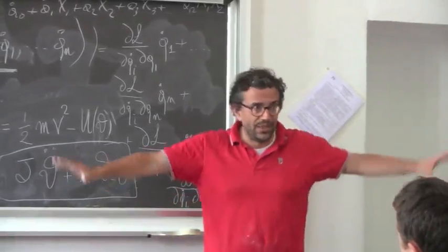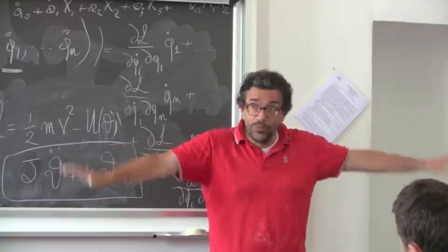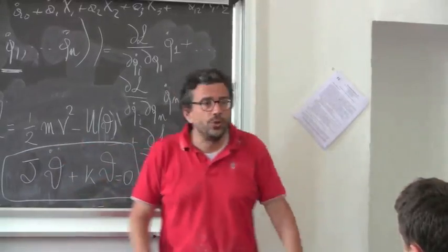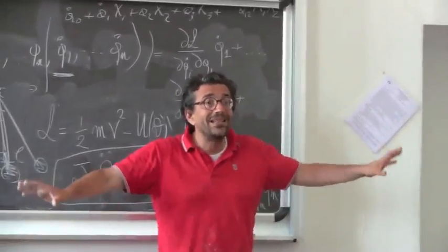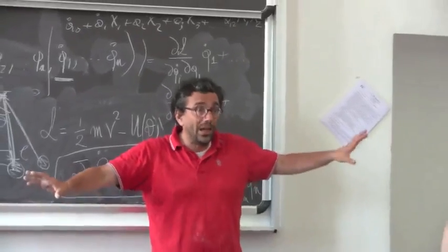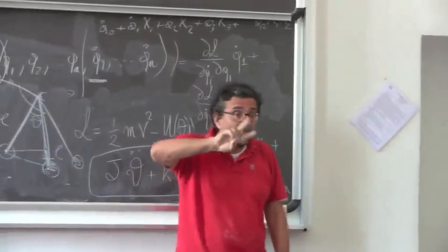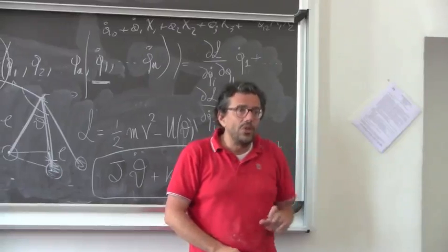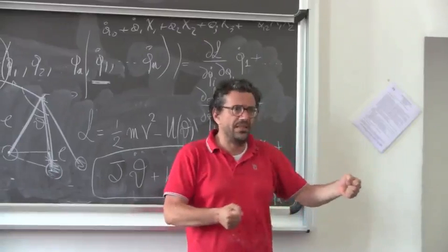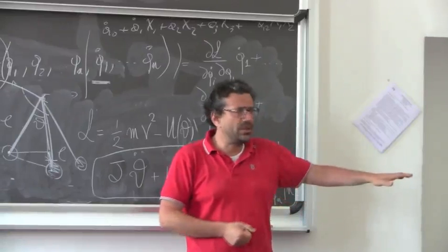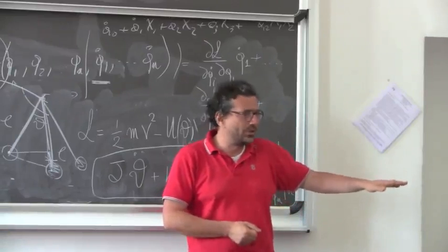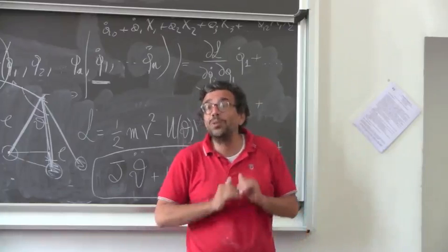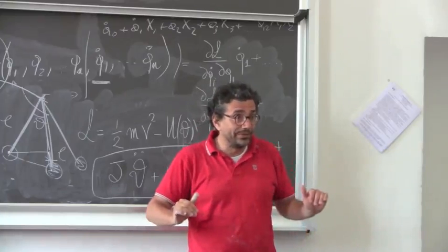You have seen the wings of the airplane. They are moving a lot. Why? Because you need to exploit their mechanical resistance a lot if you want to optimize the ratio of weight to resistance. You can build a wing very resistant, which is not deformed under the aerodynamical loads. If you do this, what will happen to your airplane? It will never take off.